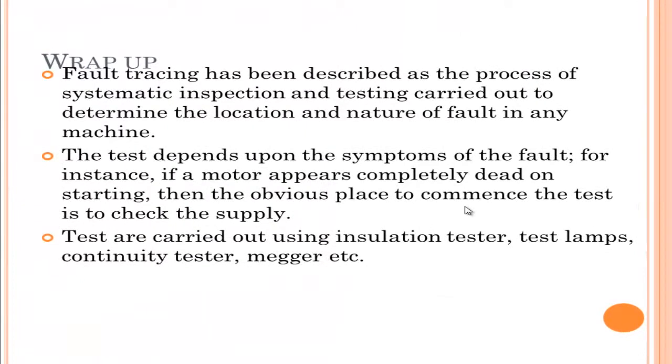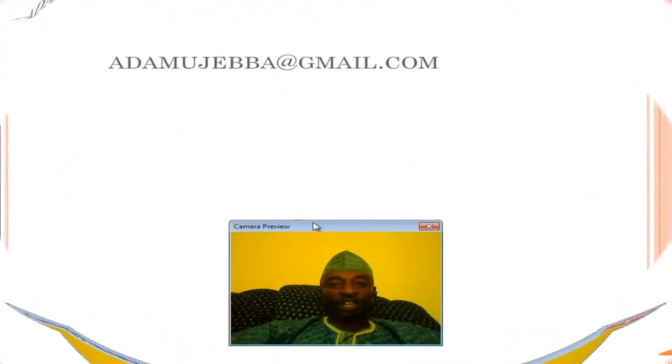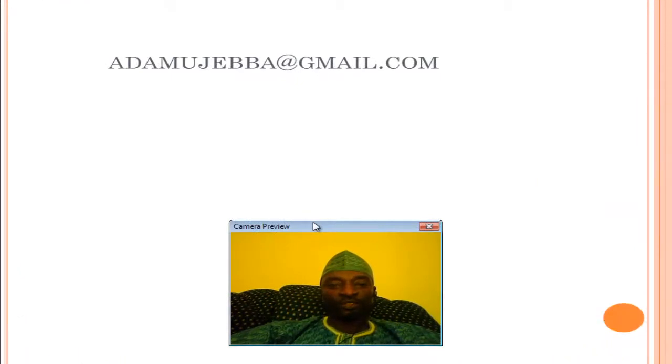Now, by way of summarizing our discussion for today, we have talked about fault tracing. I would say fault tracing is the process of systematic inspection and testing which is usually carried out to determine the location and nature of a fault in any machine. We also said that the test depends upon the symptoms of the fault. For instance, if a motor appears completely dead on starting, then the obvious place to commence the test is to check the supply. Then we also mentioned that tests are usually carried out using an insulation tester, test lamps, continuity tester, as well as a Megger.